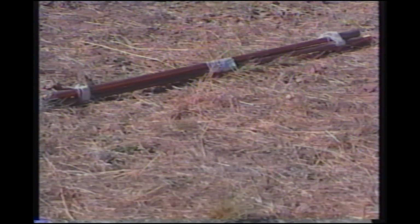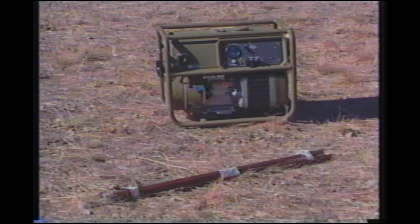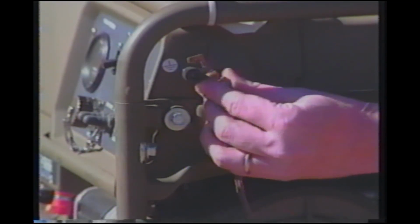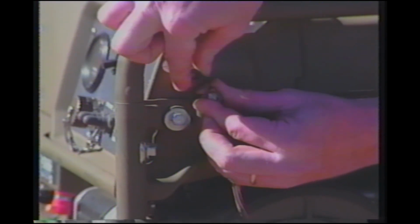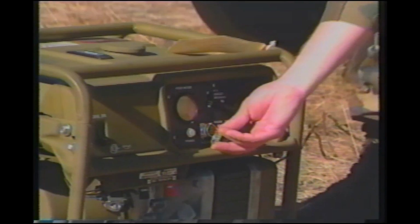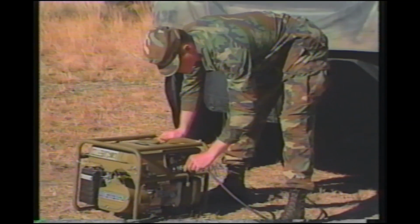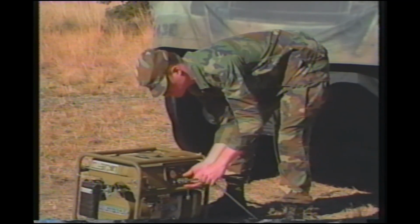The next step in preparation is the grounding of the generator. A 3-section, 9-foot-long ground rod is provided. Grounding procedures may vary. Refer to TC11-6 for other grounding methods. Securely fasten the ground wire to the ground terminal on the generator and the ground rod. Now, remove the dust cover from the AC receptacle on the generator and connect the thermal element power cable to the AC out receptacle.